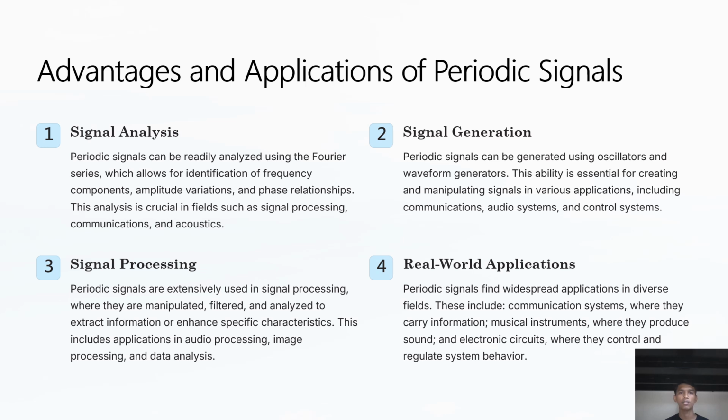Advantages and applications of periodic signals. Signal analysis: periodic signals can be readily analyzed using the Fourier series, which allows for identification of frequency components, amplitude variation, and phase relationships. This analysis is crucial in fields such as signal processing, communication, and acoustics.